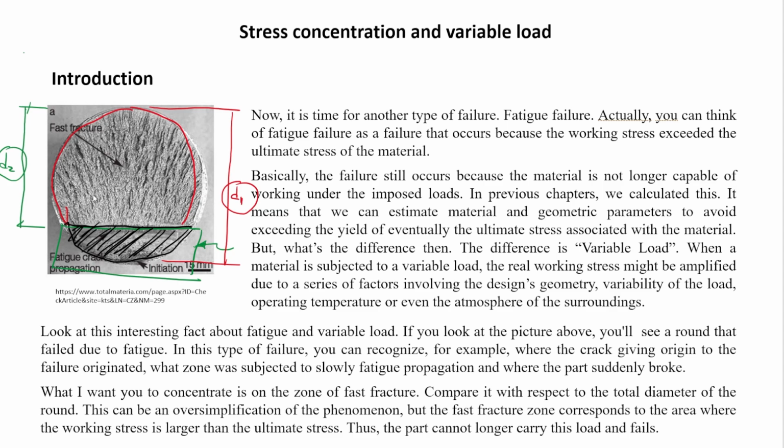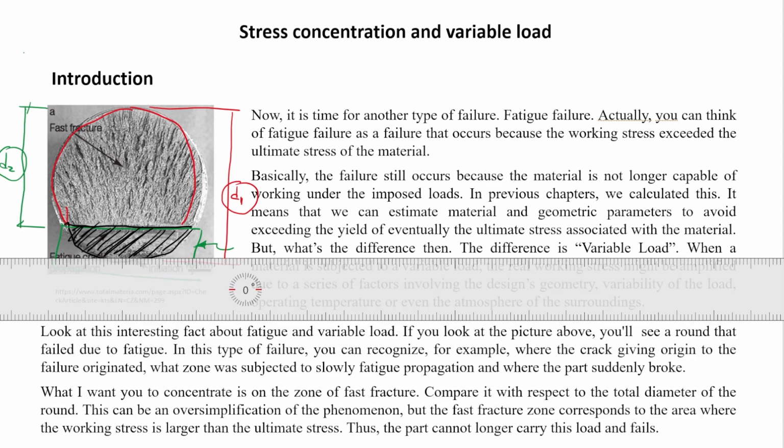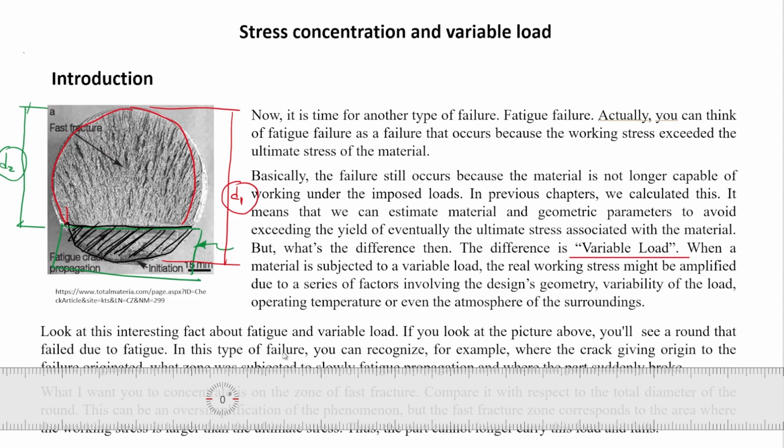And one of the specific characteristics of fatigue and fatigue failure has to do with this thing here. This is called variable load. In the static case, we don't consider fatigue as a predominant failure mechanism. In equipment, machine elements that are moving or subjected to a variable loading, then we can say that yes, fatigue might be a possible failure mechanism of that part.